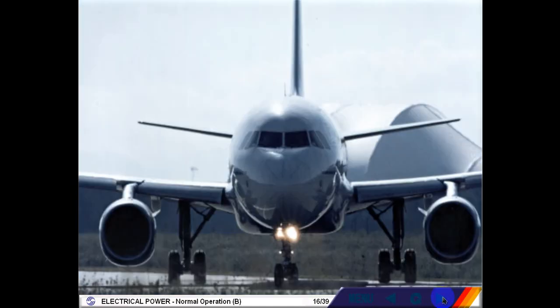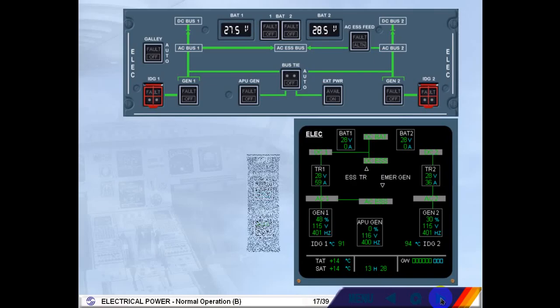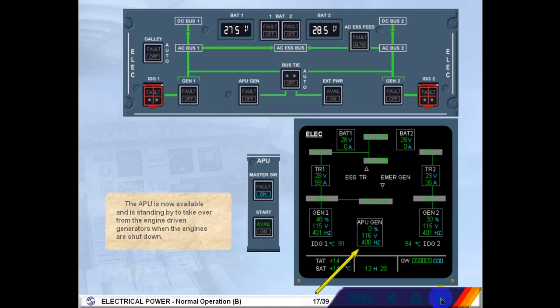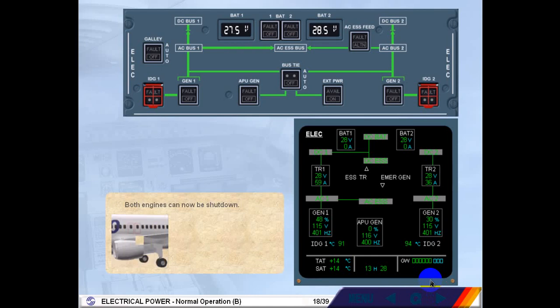We have just landed and are taxiing to the gate. We will start the APU for you. The APU is now available and is standing by to take over from the engine-driven generators when the engines are shut down. Both engines can now be shut down.